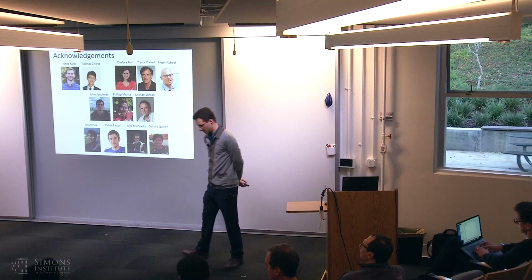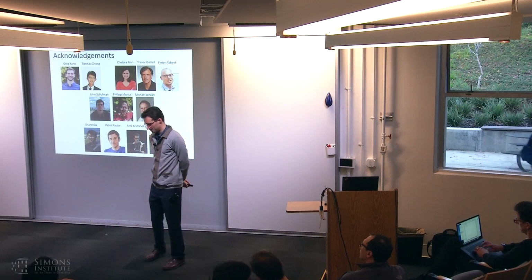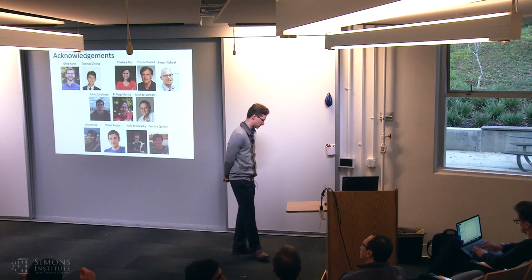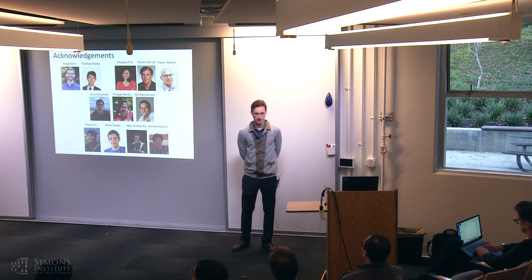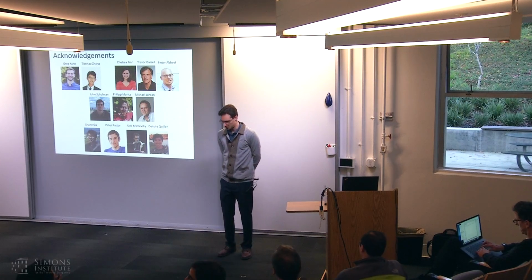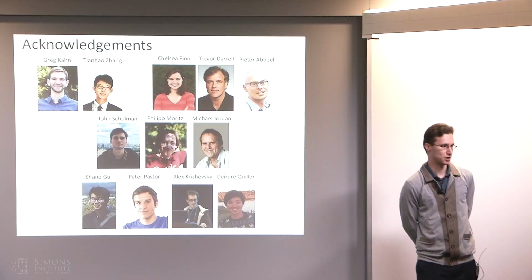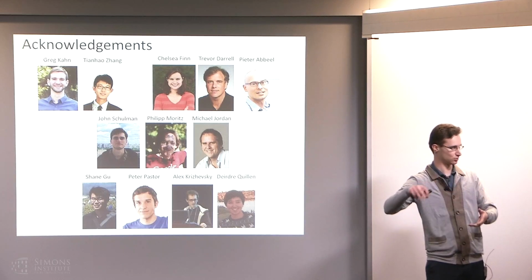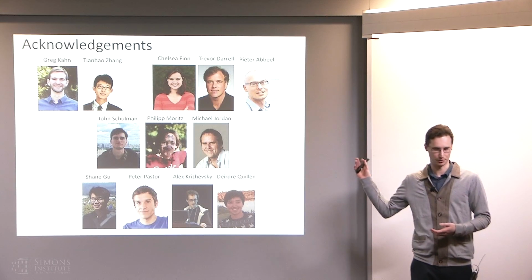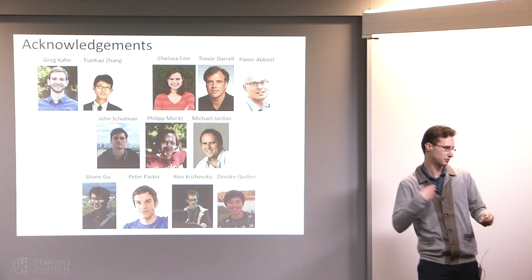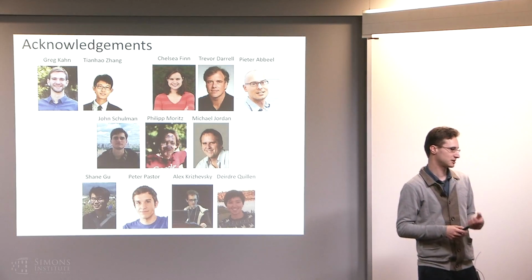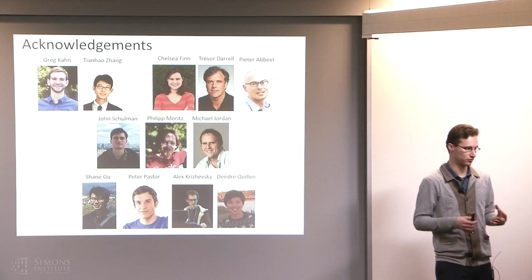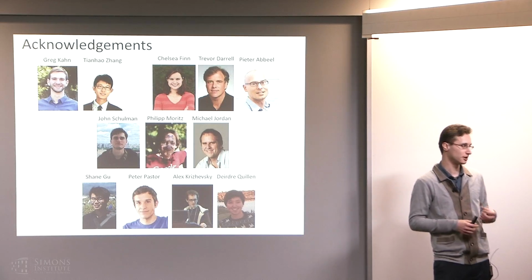Yeah, there are a few ways to do this. One very classic approach that bridges the gap between model-based and model-free is what's called the Dyna algorithm. What that method does is actually very simple. You fit a model of the dynamics to your data, and then you generate a bunch of artificial rollouts from that model. You need to generate some samples in order to compute the policy gradient. Usually you would do that by running something in the real world on your robot, but here you fit a model and just generate fake synthetic data from that model. That's a fairly straightforward and simple way. Now maybe there's more to be gained from a more nuanced approach where you integrate these methods more closely, but that's just one example.